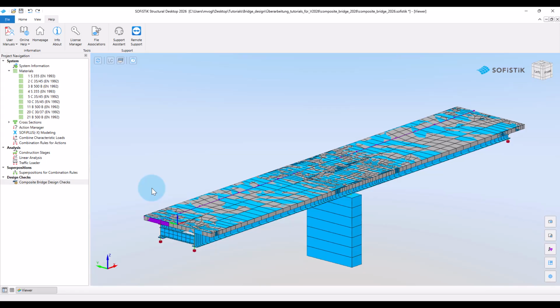In our case, we get this by combining the non-cyclic actions to give the minimum bending moment My, because this gives the highest chance that the concrete is in tension, therefore assumed to be cracked, so giving the least sectional resistance. Okay, now let's start.